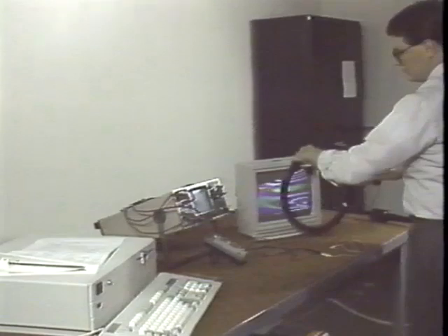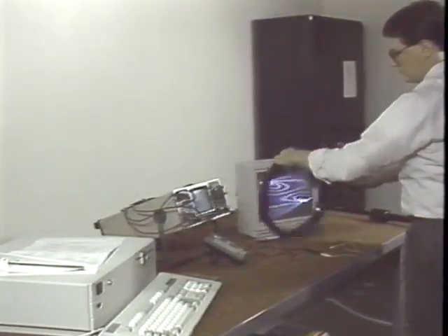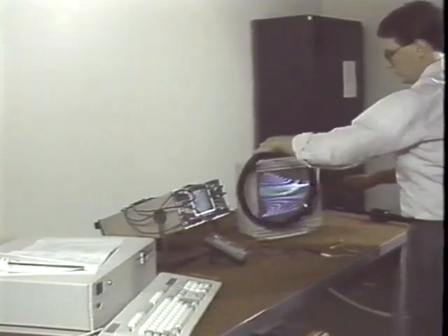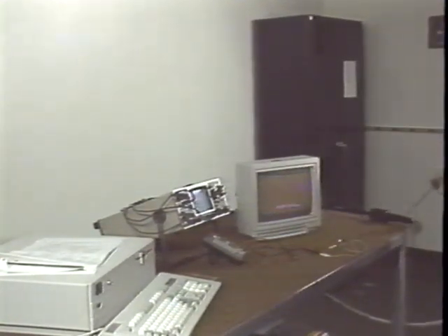Once you have passed the degaussing coil in front of the entire CRT, move the coil around both sides and the top of the screen. Then back away from the unit. Do not turn the coil off until you are about 6 feet away. Once this is done, you may begin the color alignments.